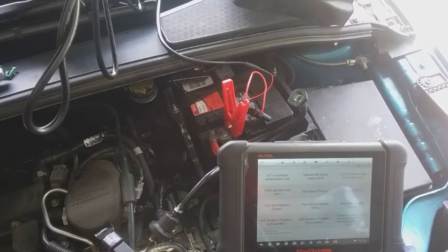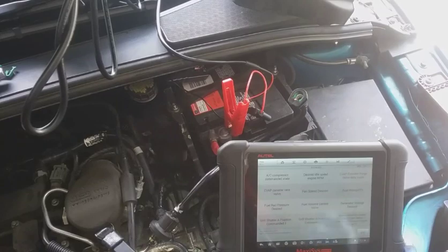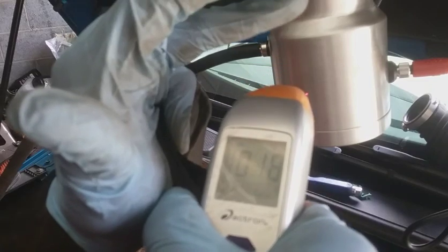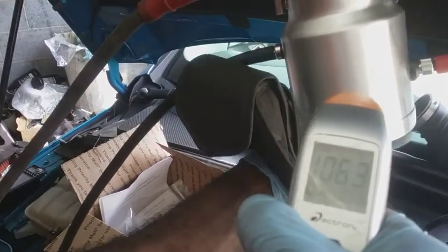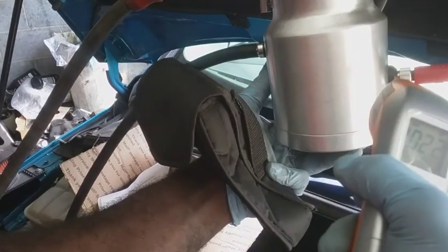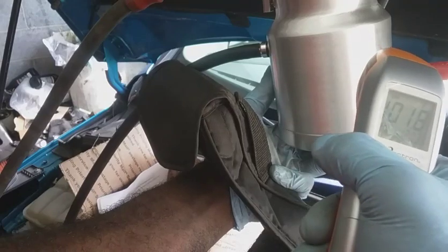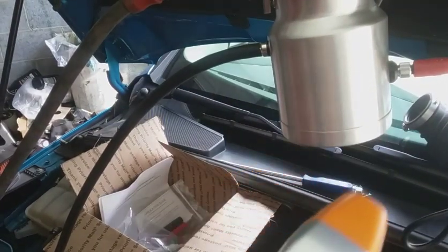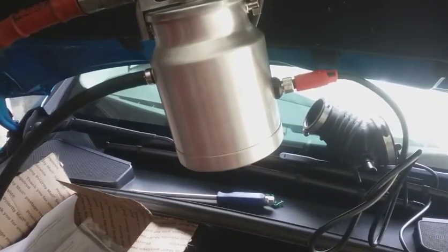All right, let's do a resistance check and see if it's within specification. I also want to get a temperature reading. I just cut it off. It's at 102 degrees. Now my battery's about to die. 99, 100. It is a little warm though. I feel like it's hotter than that, about a heating element. So 110 was the hottest. That's what temperature it is, and I just disconnected it like 60 seconds ago.